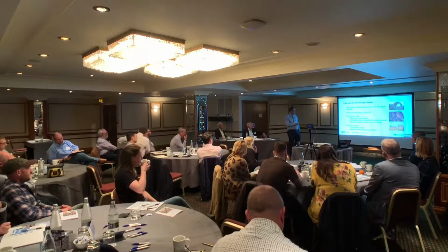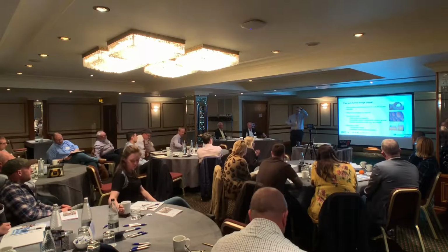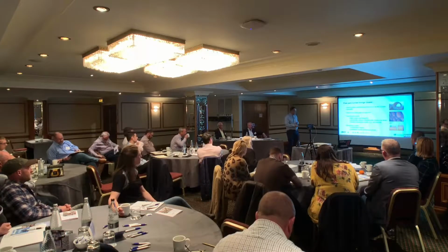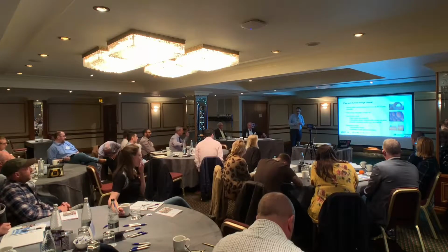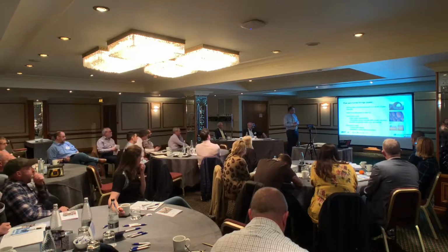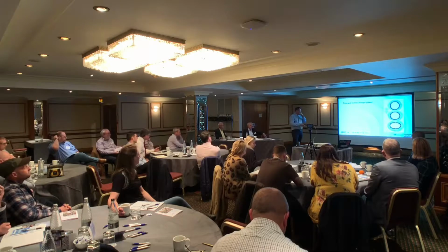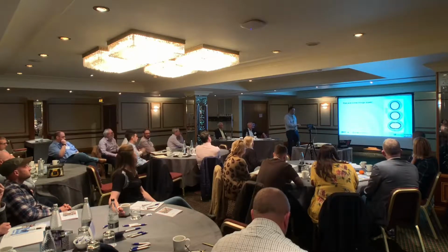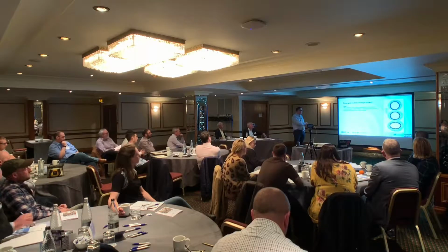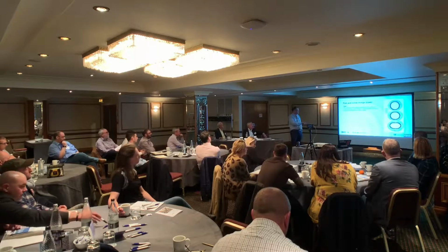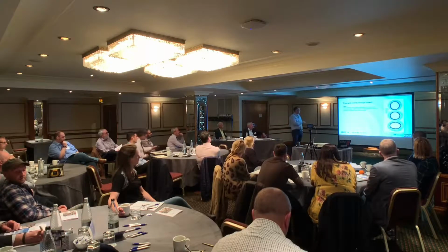So if you like, the permanent loads may be concentrating on the loads that are surrounding the pipe and then being pushed on from above. And the installation loads at the bottom, they're the linear loads, so it's the jacking process itself. In terms of the importance of that, just on the side there, this is basically the mechanism. So you've got a pipe in the ground. The pipe at that stage, if you've not considered your design properly, you may start to get some cracking.